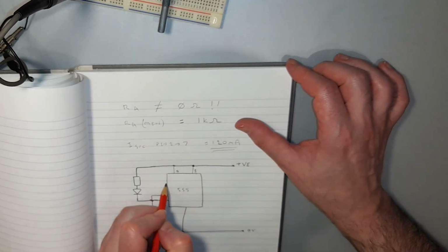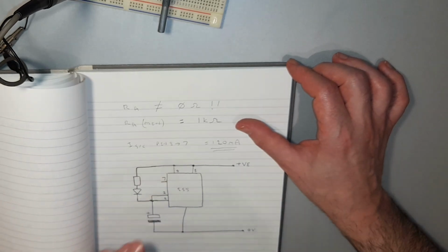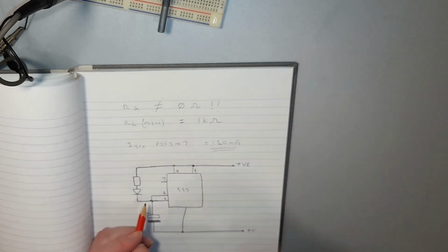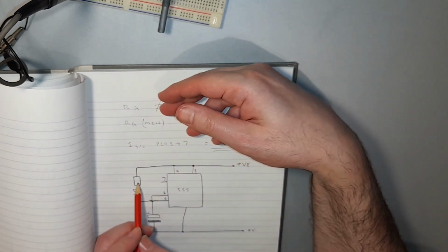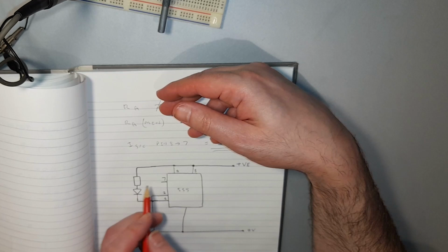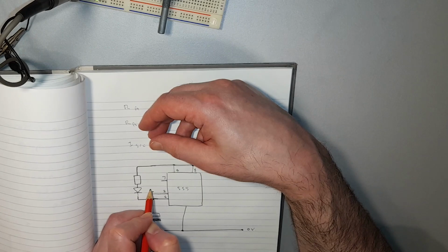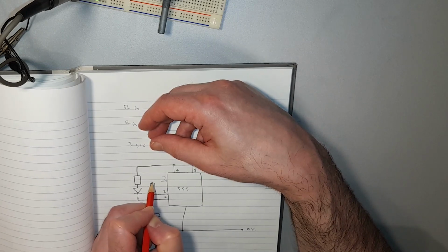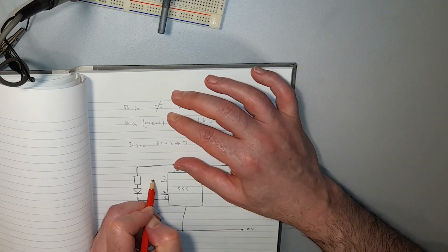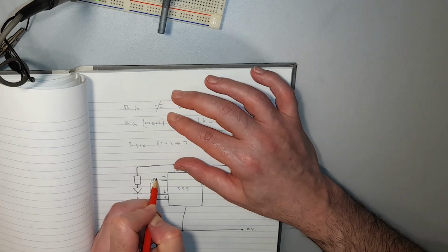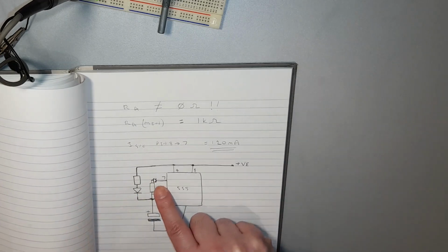And then to discharge, we need to discharge through pin 7. So here's pin 7. And here we want to have a different value resistor, which is the same value as that resistor, and another steering diode. So if we put the resistor here and a steering diode here, like that. There we go, that's a steering diode. Didn't draw it very well, but I hope you can see that.